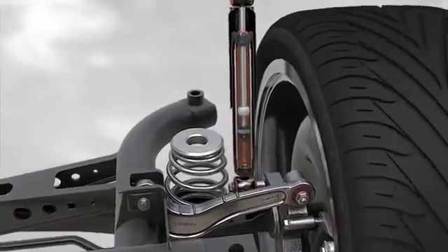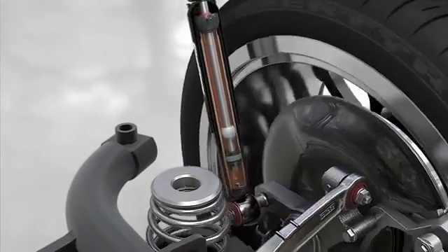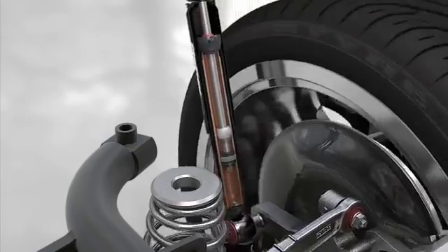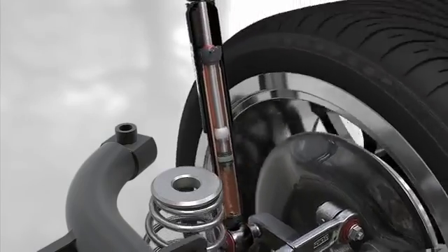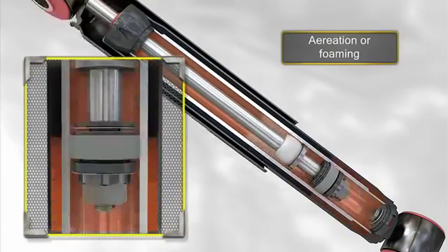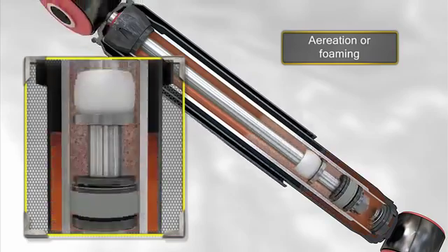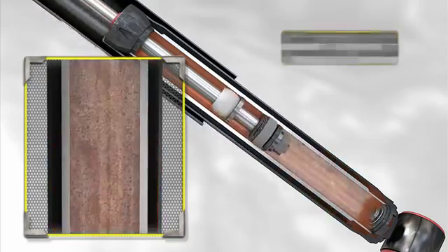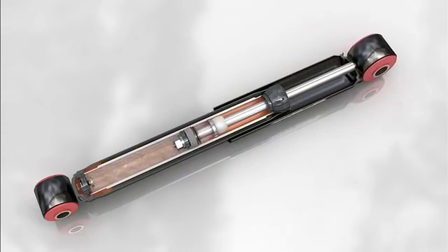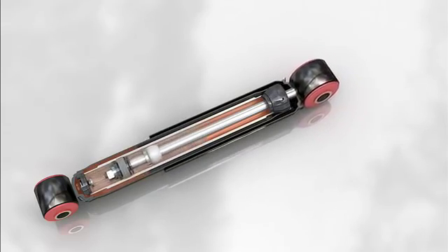The key advantage obtained by adding pressurized gas to the twin-tube shock absorber is that it avoids the phenomenon known as hydraulic fluid aeration or foaming, which appears when air bubbles form in the oil due to excessive pressure changes occurring when the oil flows through the piston valve as it moves up and down at high speed. Aeration causes noise and inconsistent shock absorber performance due to the air flowing through the valves.